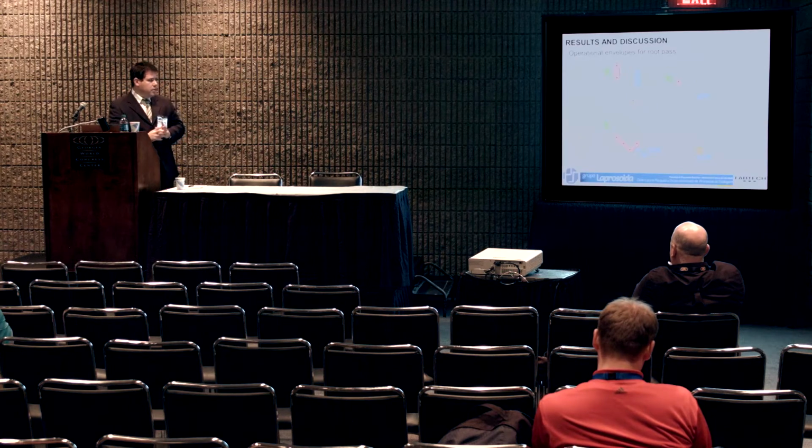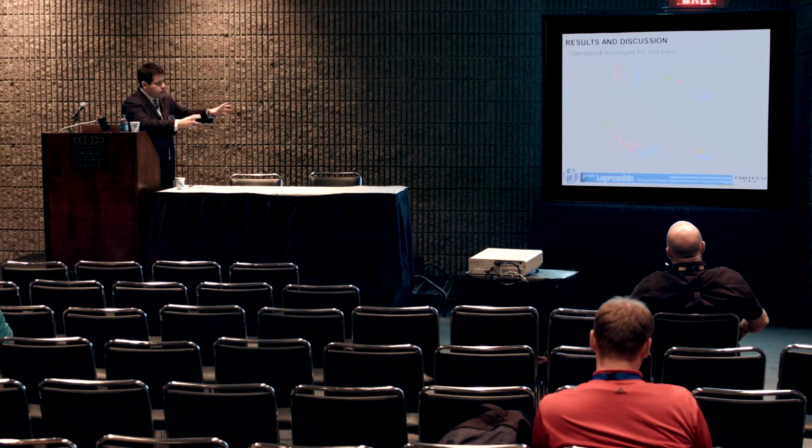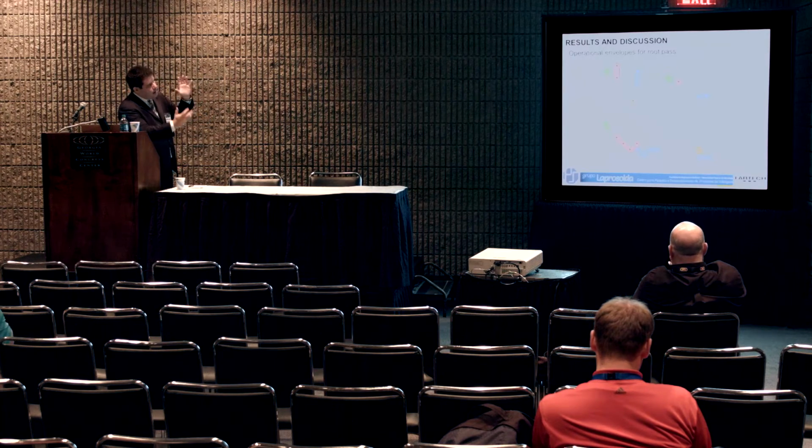That's another issue: how much high-low you may have. In our case, 1/16 is in accordance with API 1104. So yes, we can weld with all those processes. Some have more points to be welded, some fewer, but we can weld with all of them.